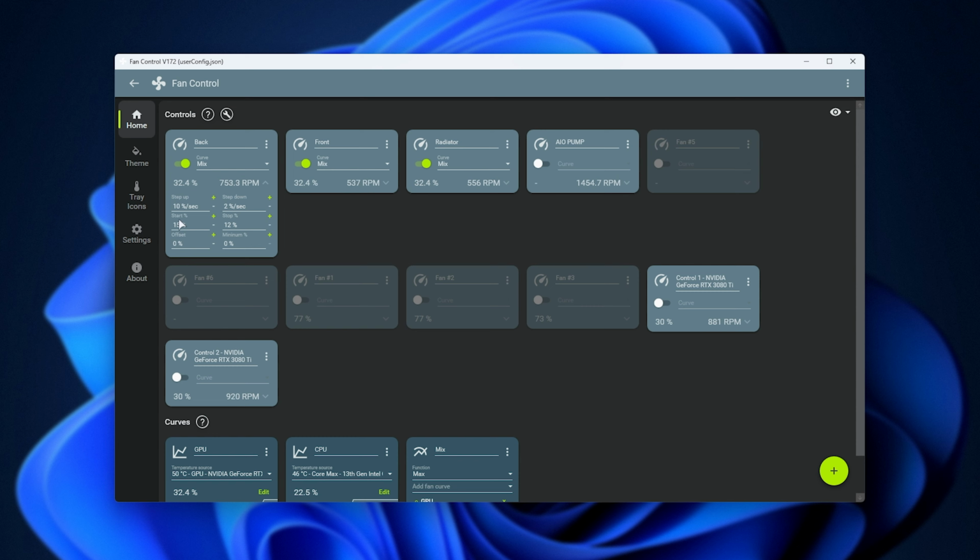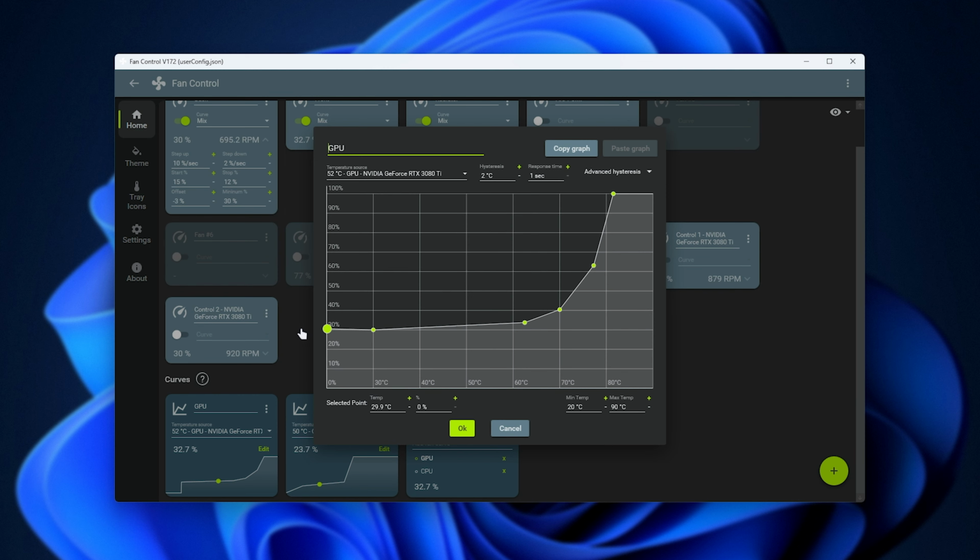You can set a start percentage and stop percentage. These are automatically set, so you don't really need to worry about them. And finally, offset. If one fan is running faster for some reason compared to other ones, these are all the same fan, so they should be running at the same speed as they have the same percentage, but this one over here is a little bit faster. We can change this using the offset percentage here to slow it down to more accurately match other fans in our system. Just as an example, we can also set a minimum fan speed, for example, of 30, so our graph will look something a bit more like this, even if the actual graph goes lower than this.